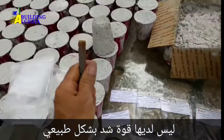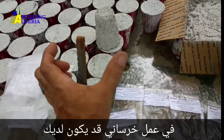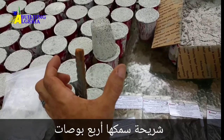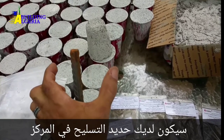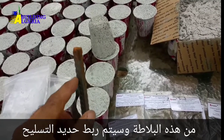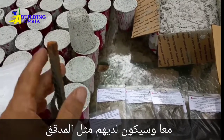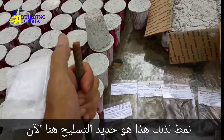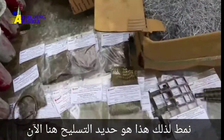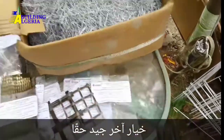Normally in a cement job, you maybe have a slab that's 4 inches thick, and you'll have rebar right in the center of that slab, and the rebars will be tied together in a checker pattern. So that's the rebar here. Now another option that's really good is this here.